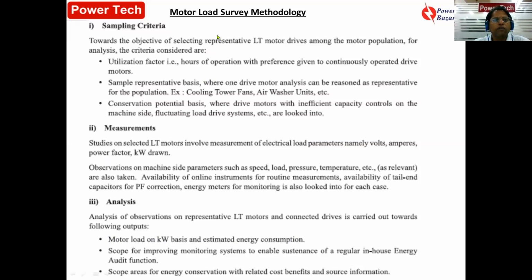Now, how to do a motor load survey? Why is a motor load survey required? In very old industries, there are a number of very inefficient motors which take a lot of energy, and losses are very high. Winding failure has happened, and now we need to change the motors. So you need to understand the motor size. Sometimes the nameplate is missing, and you don't know the size of the motor or which motor to replace. So for a motor replacement program, you need to conduct a motor load survey.